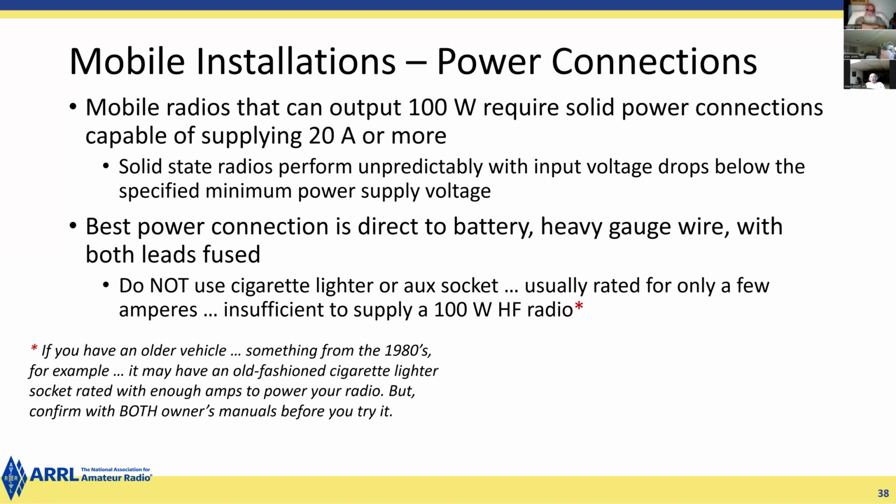With the ignition off, the electronics in your car draw very low amounts of current. Less than 1 milliampere is typical for the whole car. The reason for that is, typically you should be able to start your car again after it's been sitting for a month. Or for instance, you go off on vacation for a few weeks and leave your car at the airport. You want to make sure that it can start when you get back and you're tired and you just want to go home.